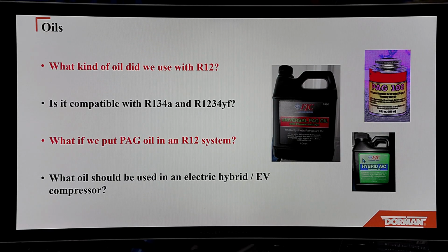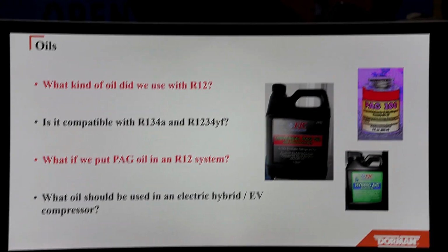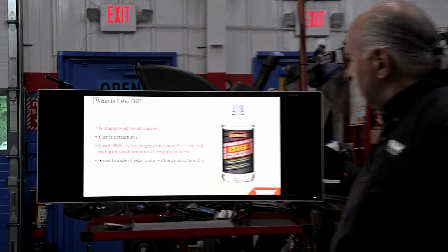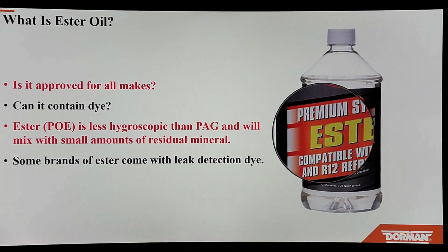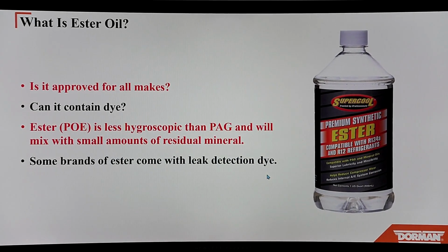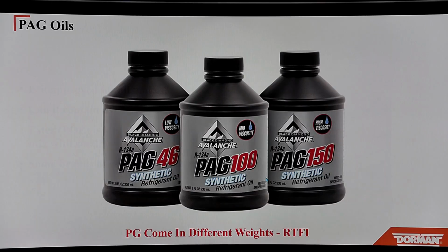It does not go in the compressor. I want to stress that again. It's not made for the compressor. Buy the right oil for the compressor. And here's a universal ester oil. It's approved for all makes. It can contain dye, but you don't want to use that in the compressor.